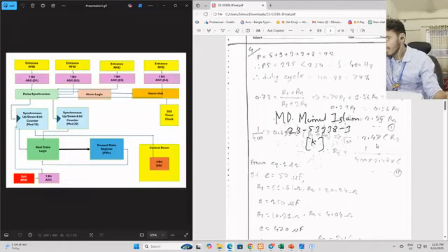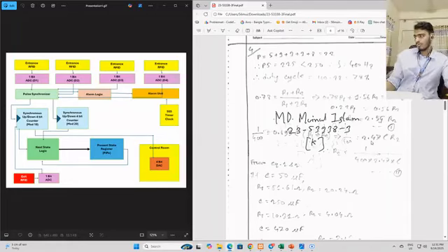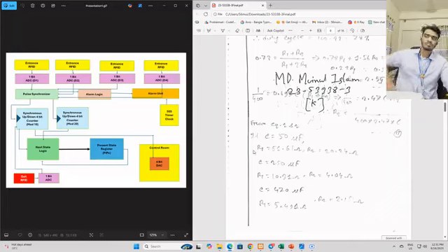Again, we need a capacitor for the timer IC. We have been given three different capacitor choices: 50 microfarad, 250 microfarad, and 470 microfarad. I have computed all the resistors for 50, 250, and 470 microfarad. The lowest resistors we got are for 470 microfarad, and the highest resistors we got are for 50 microfarad, which are 51.61 ohm and 20.24 ohm. Now we choose the 50 microfarad and these two resistors.